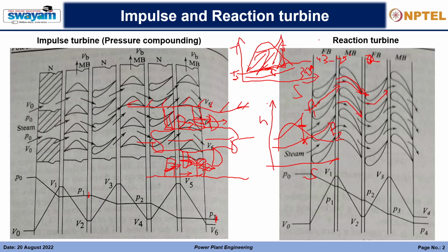So there will be some vacuum, but we are restricted by this. There should be at least 10 degrees Celsius difference in order to cool down effectively. If we go beyond this, then there won't be any cooling, because the thing where we are applying the cooling water has a higher temperature than what we need to cool down, right? So that is why we cannot go beyond.